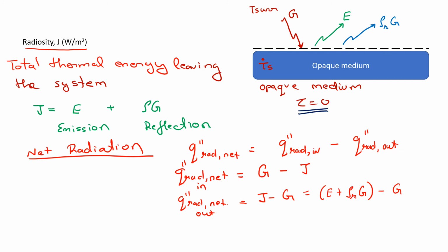Okay, so we saw that we have an opaque surface, so our equation will be the summation of rho R plus alpha plus 0 equal to 1, or alpha equals 1 minus rho. So in this equation you can write the emission that's emitted by radiation as epsilon, that's the emissivity. We've seen this equation in chapter 1.